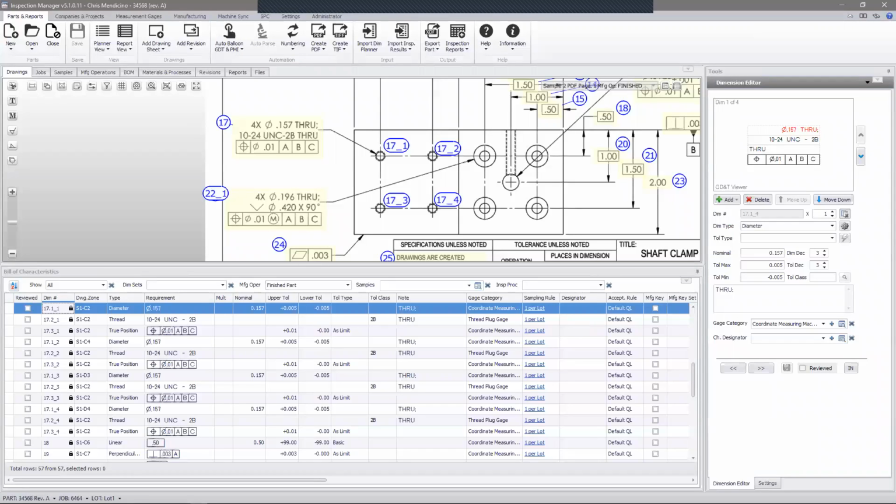We need to maybe address bonus tolerance for applicable GD&T. This is a question that needs to be addressed, and probably educate about bonus tolerance for GD&T. Yeah, we can follow up if there's specific training needed on that for the customer. But we can discuss it. Yeah, it's definitely something that we do, though. As far as GD&T and bonus tolerances go, we can take that data from the CMM directly for the output on the GD&T, and it's able to be reported on. And the pass-fail analysis is based on that bonus tolerance availability, and all that's handled quite well and elegantly.